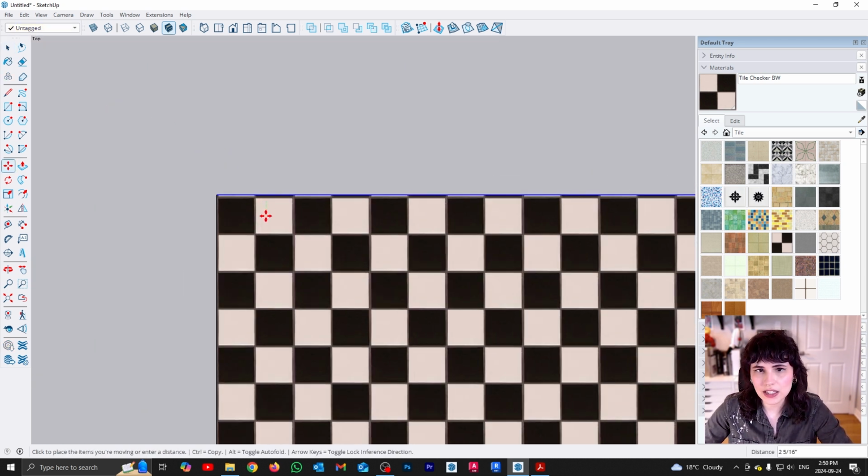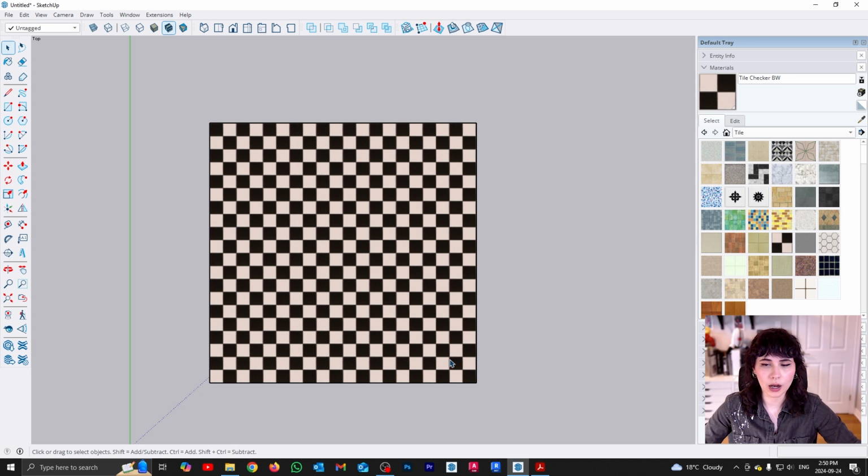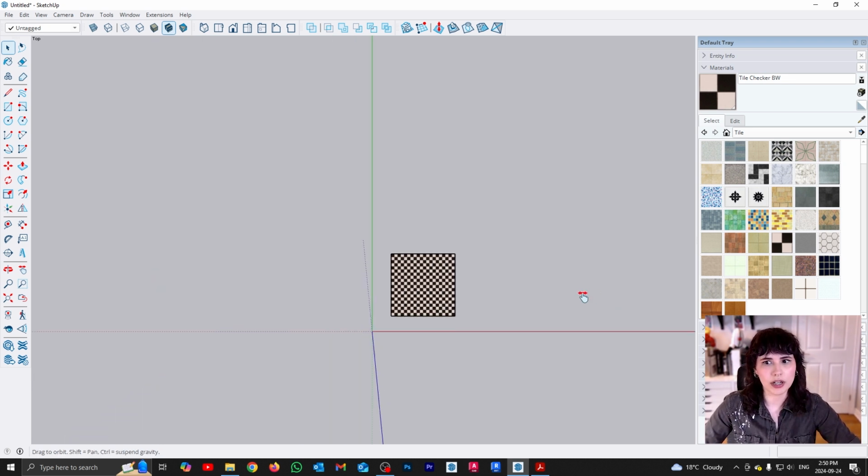So this is the easiest way that you can make sure that your SketchUp geometry matches the texture that has been applied to it. But this is a rare scenario because basically what I am doing here is I am not concerned with deforming my geometry to make it match my image. Usually it's going to be the other way around. Usually you're going to want to deform the texture to fit the geometry. So let's see how we would do that with another example, which is going to be an area rug, right?